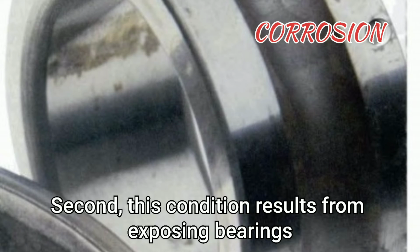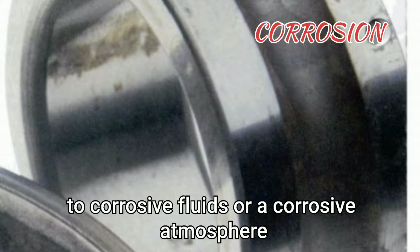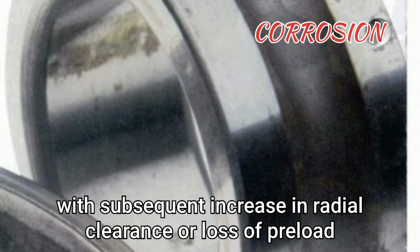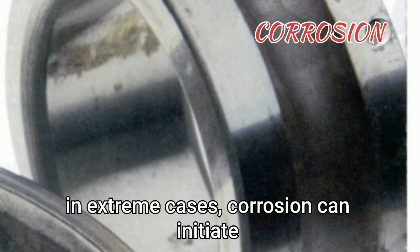Second, this condition results from exposing bearings to corrosive fluids or a corrosive atmosphere. The usual result is increased vibration followed by wear, with subsequent increase in radial clearance or a loss of preload. In extreme cases, corrosion can initiate early fatigue failures.